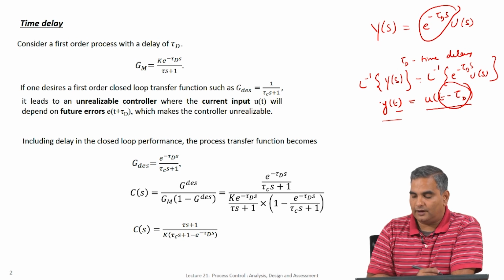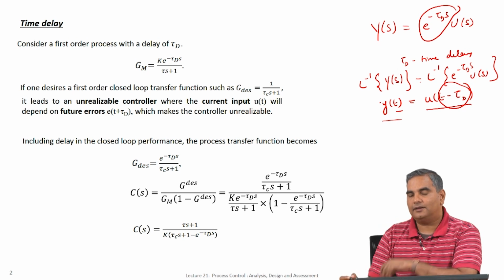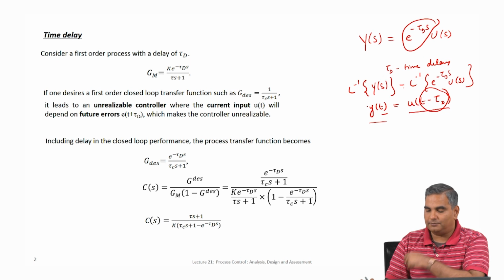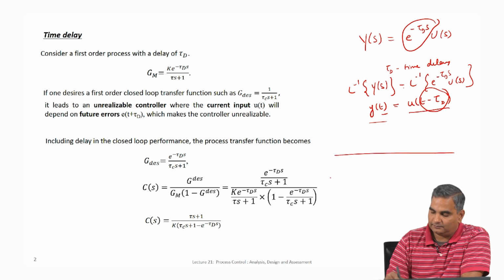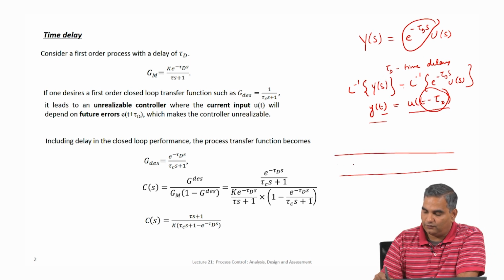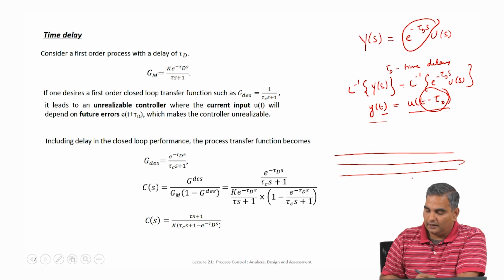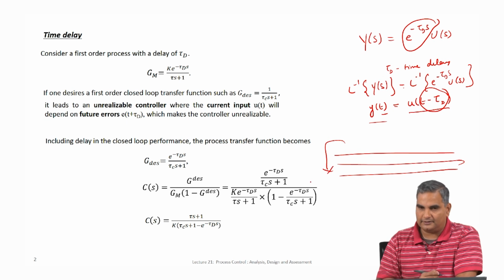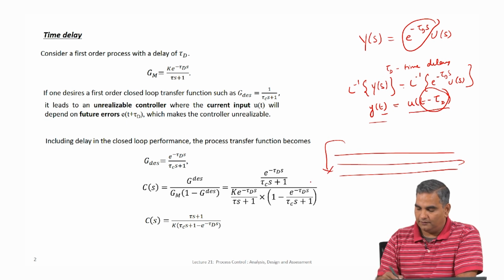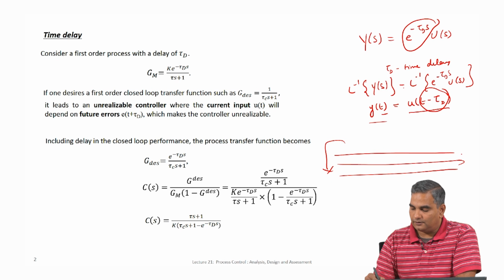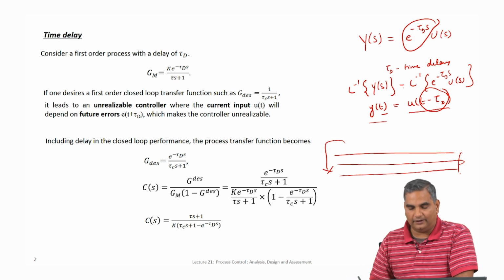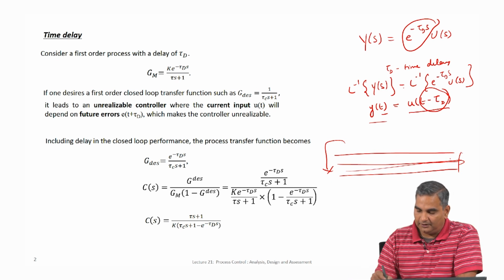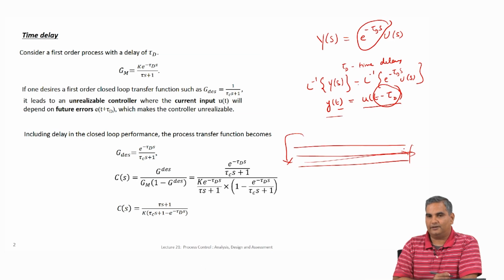Okay. So, this is the idea of time delay, and this is something that you see in real life. For example, if you have a long pipe, let us say, at steady state the flow is constant, and then suddenly you increase the flow here. Now, the effect of this increase in flow is not going to be felt here right away. All this intermediate liquid has to go out before this high flow reflects here.